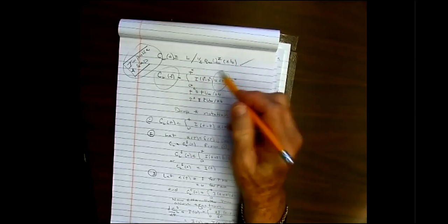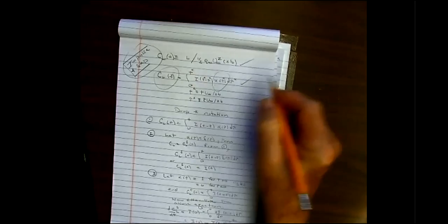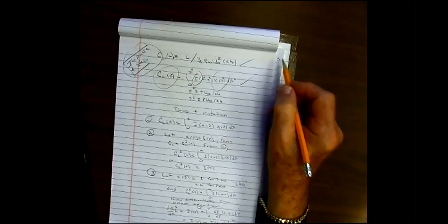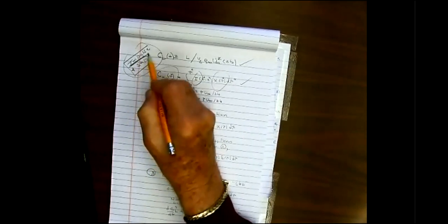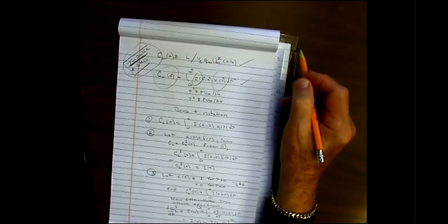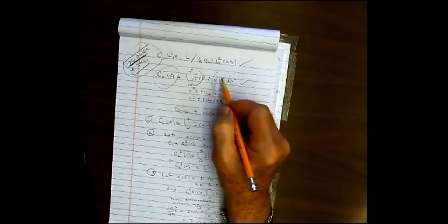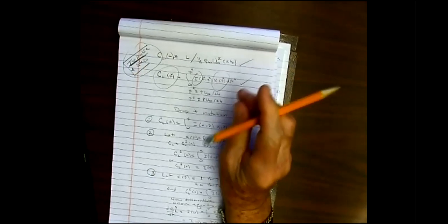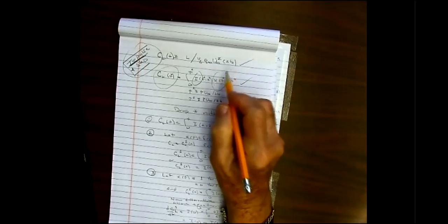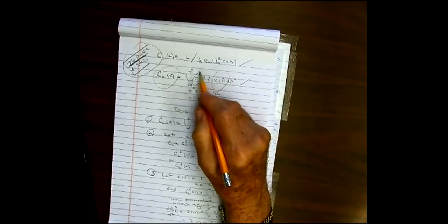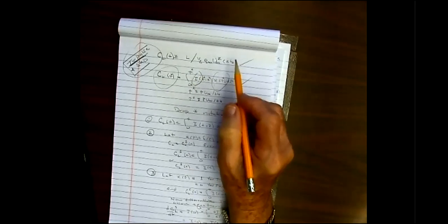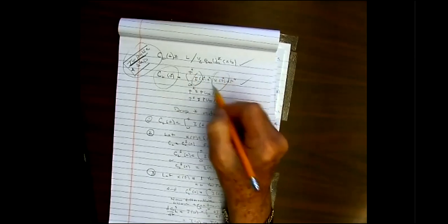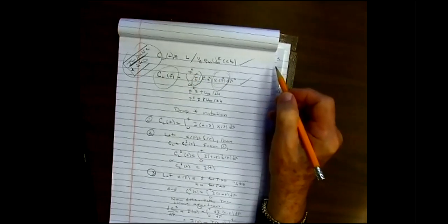And I can always write it in terms of this convolution integral, where there is some function I. I use the symbol I because I'm going to think of that as related to an impulse. And therefore, if I find the solution for an impulse in alpha or a step change in alpha, that will allow me to determine I. And once I have I, then I can use this equation over and over again to find the lift for any old alpha of tau.